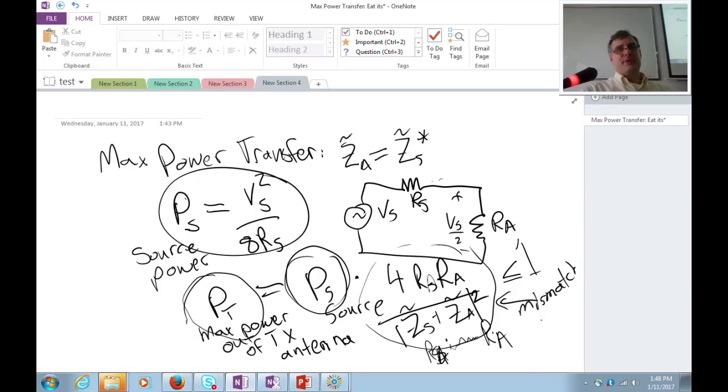And the other thing is that your antenna may not be very efficient. It may have a low radiation efficiency. That is, I'm coupling power into the antenna and it's trying to radiate out. But maybe there is something about the antenna. There's ohmic losses because you can't make antennas out of superconductors. Likewise, there's going to be some dielectric materials nearby. Those also can provide loss to an antenna in the near field.